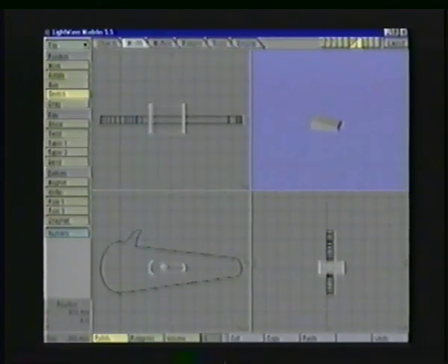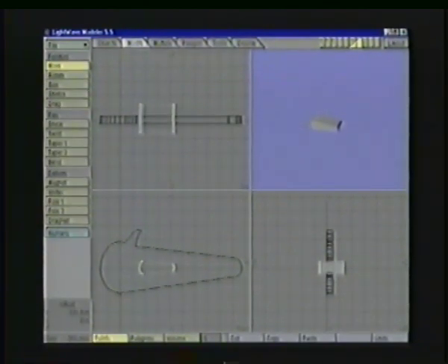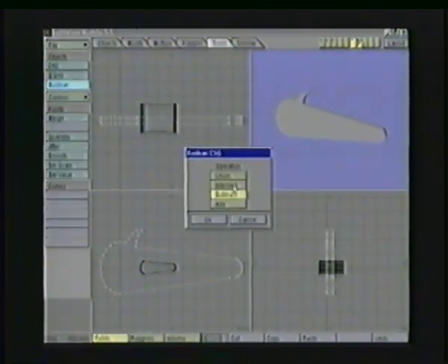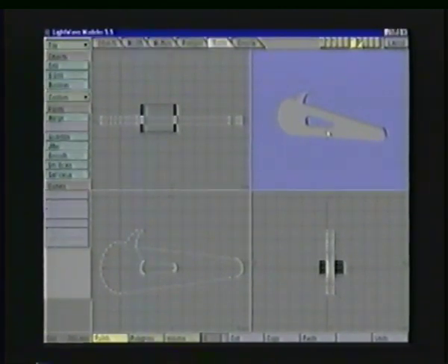When I'm happy with the shape, I can then hit T on the keyboard to move it into position where I want to cut, swap layers with the apostrophe key one more time, and I'm going to Boolean subtract. Boolean's under the Tools panel, and that cuts the hole right through.